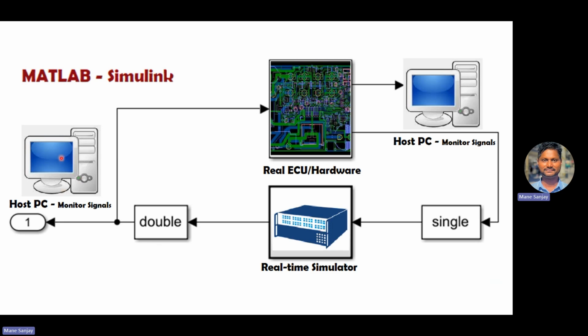But again, the host PC also plays a very important role. You can generate the executable files of your model and flash them into the real-time simulator. If you are simulating the coolant temperature, the battery model, the state of health, or motor winding temperature, whatever you have simulated, you have to generate the executable file and flash that file into the real-time simulator.